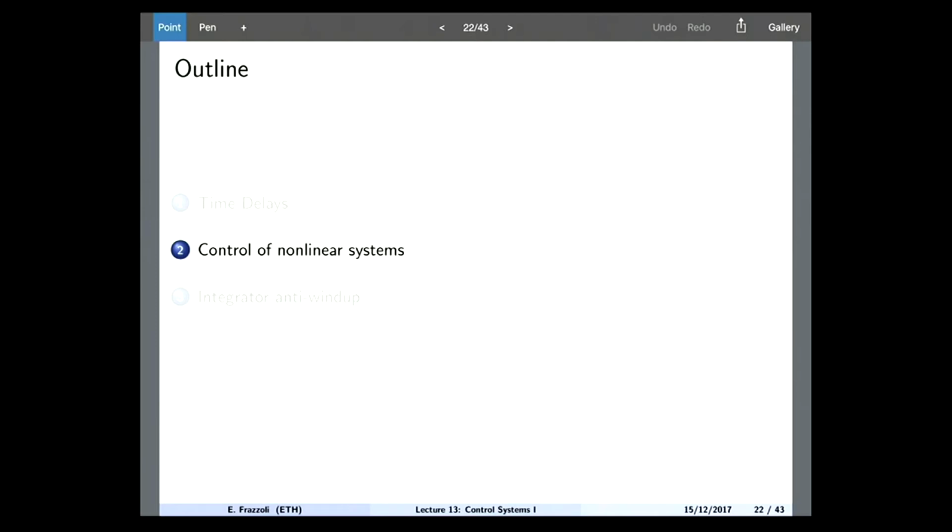Okay? When I was in your situation, I kept hearing the professors talking about the phase margin, and you want to keep it large enough, and I was always wondering, what the heck is this phase margin? I mean, where is this monster that is eating away my phase margin? Right? And then you realize that actually that monster is the time delay. Okay? The effect of time delay is to reduce that phase margin. The higher the crossover frequency, the more the phase delay will be. Okay? So let's stop here. It's a nice timing, and let's pick up after the break. Okay?